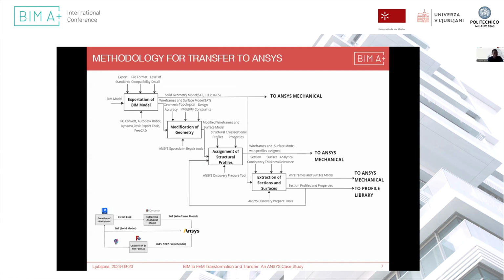And then also the BIM model was exported as a solid model to ANSYS using the SAT format, using Revit export tools. And then also it was exported to ANSYS using IGES and STEP formats, using IFC as an intermediate step, because ANSYS does not really implement the IFC, but it does so using the STEP format. And this was done using FreeCAD.